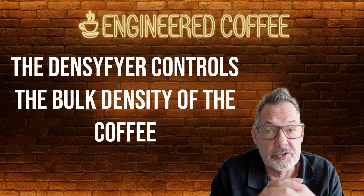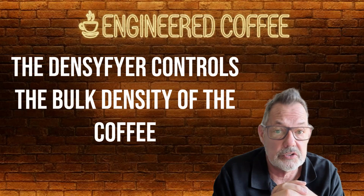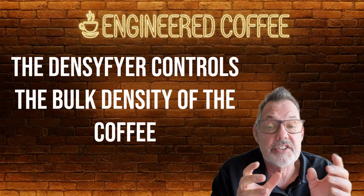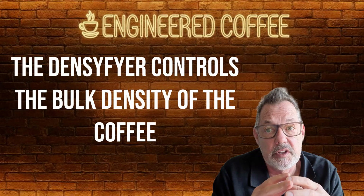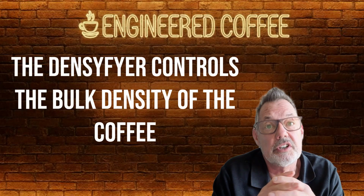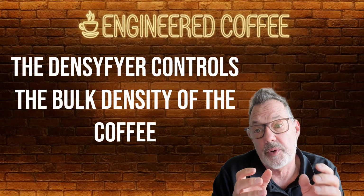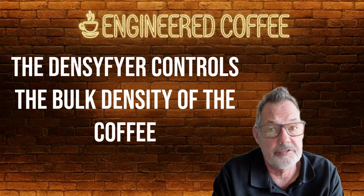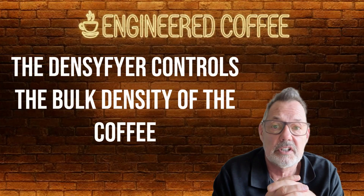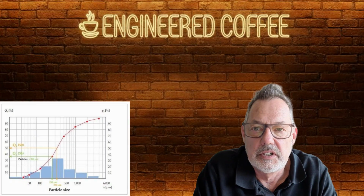The next step in the process is the role of the densifier. After grinding, another critical step is the densifier. It is often overlooked. The densifier compacts the coffee, stabilizes the bulk density, and improves dosing consistency. Because in capsule filling, you're not just controlling grams, you're controlling volume, flow, and packing behavior. If density varies, everything downstream can become unstable.